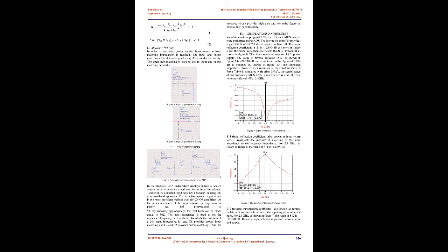3. Circuit design. Figure 6. Input reflection coefficient, S11. S11, input reflection coefficient, also known as input return loss. It represents the measure of matching of the input impedance to the reference impedance. For 2.4 GHz, as shown in Figure 6, the value of S11 is minus 12.890 dB.